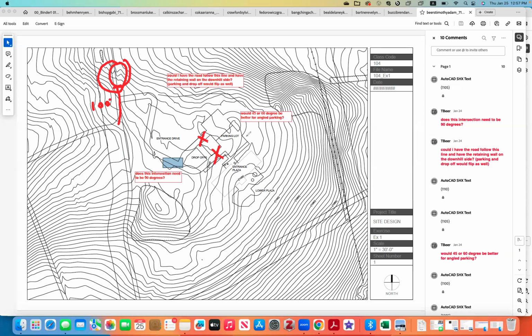So I would say first thing, lay out the parking lot. Second thing, make the dimension of the drop off correct. And then third thing, check if this is 100 feet away from the intersection. If not, then we will need to move it to be aligned either here or here. If this is within 100 feet, then we can keep it for now and get an opinion of Stuart's. And if he also thinks that that's too much trouble for grading, then we give up and we find something to create later on. That makes sense? Yes.